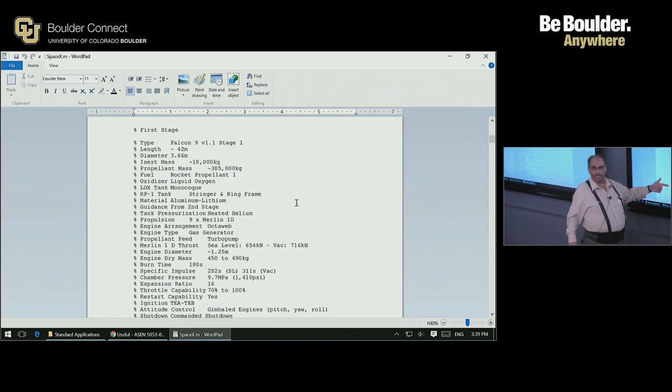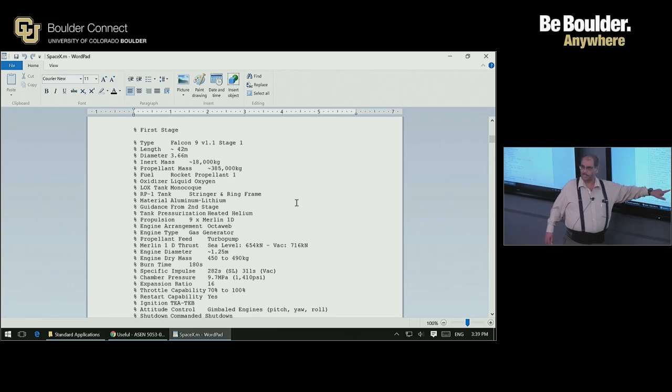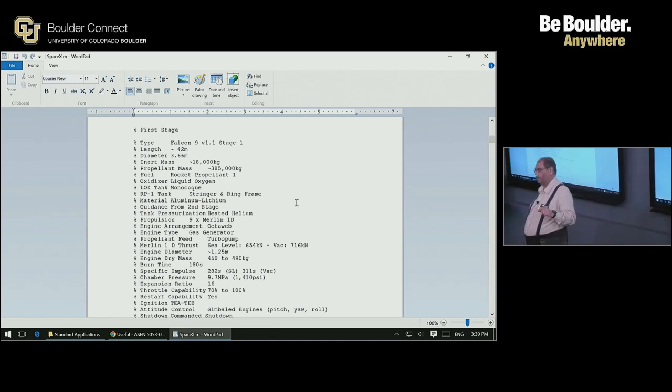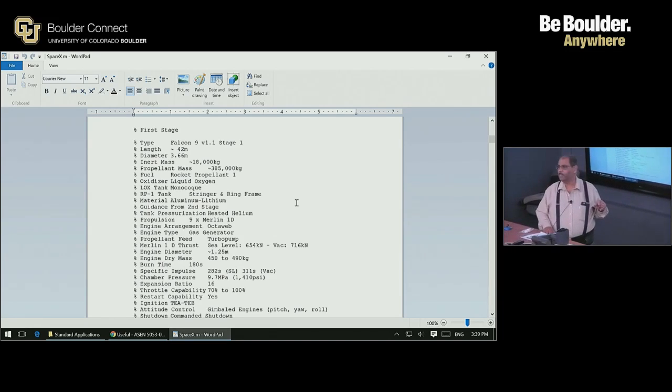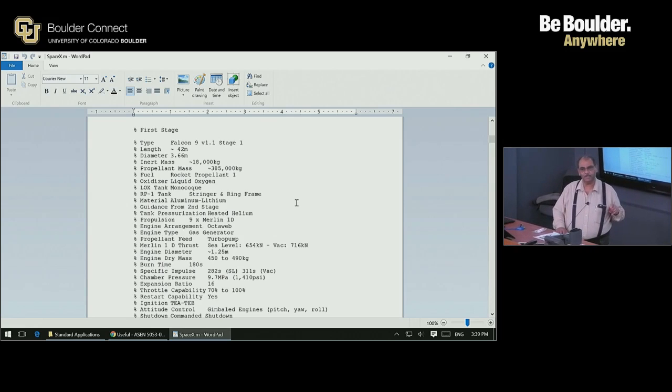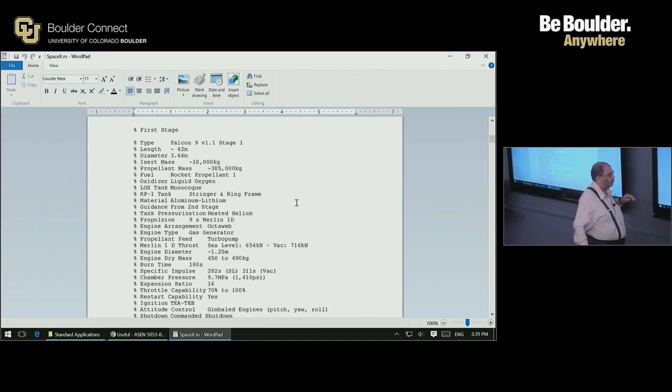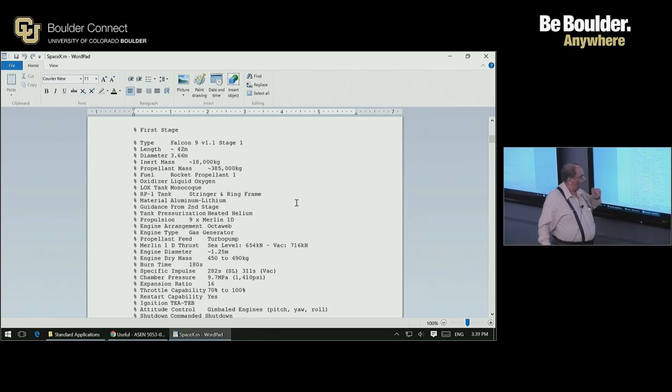Okay, specific impulse, always less at sea level compared to vacuum, the same engine. We'll see the reason why later. Okay, so when you mention thrust or the specific impulse, you must tell me whether it's vacuum or sea level. When that qualifier is omitted, it usually means vacuum. Okay, but sometimes it's not clear, so you have to be sure what value it is.